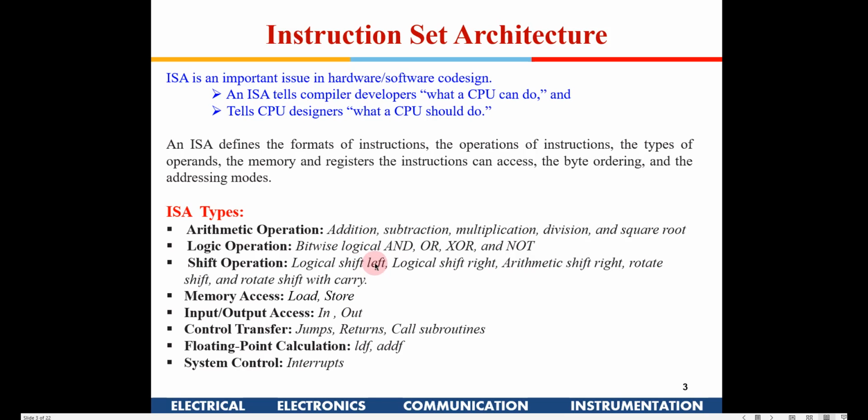Okay, I can also specify logical shift 4 times. So 4 bits from the MSB side will be thrown out of the register, and 4 zeros will be inserted from the right hand side. Okay, so that is shift left. The entire data gets shifted towards the left.